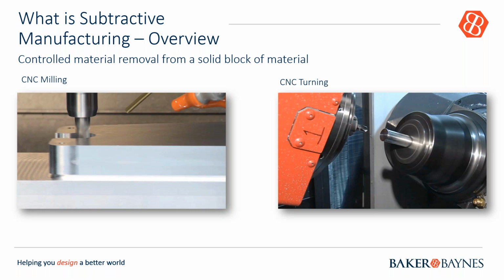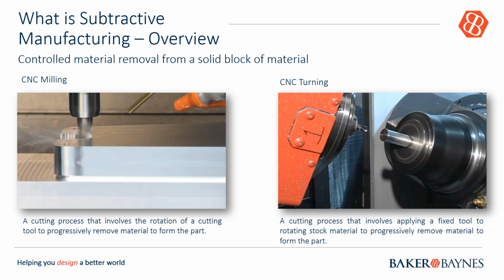This is coming straight off the HSM software, and you can see the machining profile being machined out there in the simulation. Next, you'll find the 2.5D, you can see it's coming in, it's doing some machining. It's moving in X, Y, and a bit on Z, but not actually full. And with 3D, you'll find that curved edges and fillets are achieved by using the 3D strategy, as you can see in the model orientation in there.